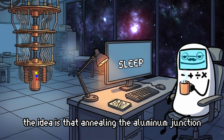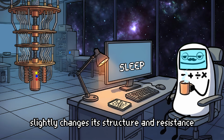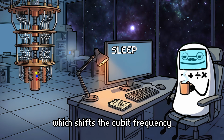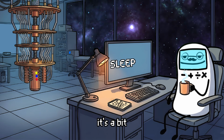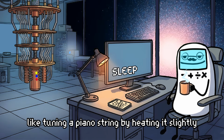The idea is that annealing the aluminum junction slightly changes its structure and resistance, which shifts the qubit frequency by a predictable and controllable amount.